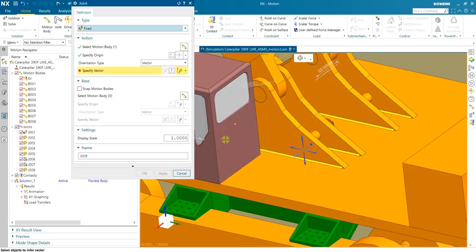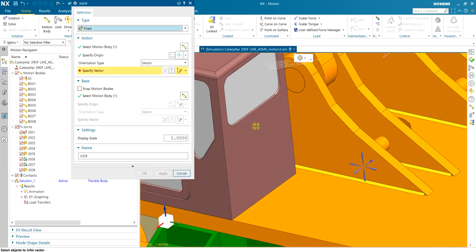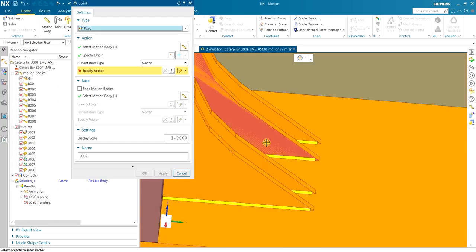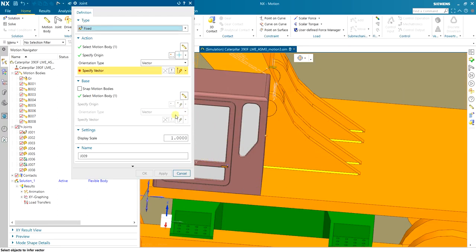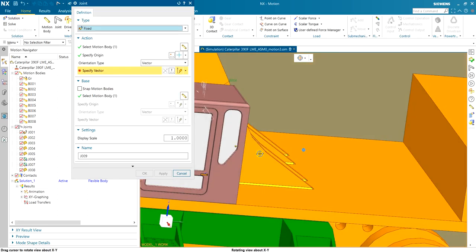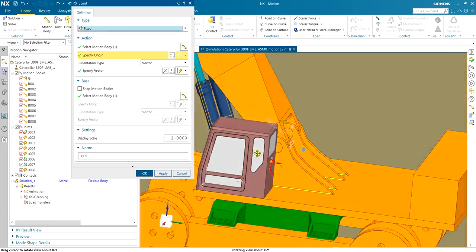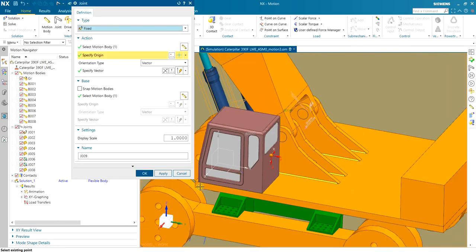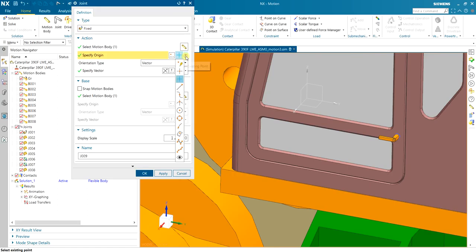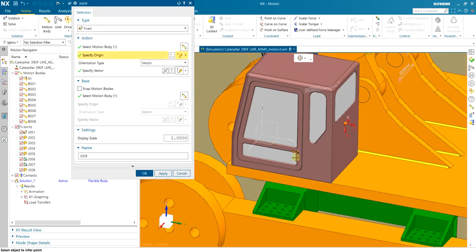but you need to be careful about the origin that you select, because this origin point should match exactly what you have in the finite element. That's where the load will be applied. So I will change the origin to somewhere known, like a point around here, maybe at the corner. That will apply all of the load to the corner, but we could select any points. But this is the reference that I already have here. This one.